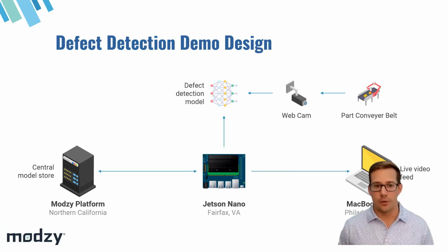With a 3D printer, we printed out some spur gears. You'll see what that looks like in a second. And on some of the gears, we manually made some defects: dents, broken teeth, scratches. You see what that looks like. We took that data set, labeled it, and trained a YOLO V5 model. This YOLO V5 model is trained hyper-specific, just a prototype, to detect defects on these small gears.